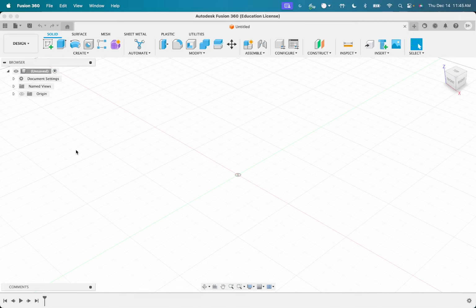Components are important because they allow you to do assembly drawings with them. You can reference them in other files, and they have more information than just a basic 3D model, which is just called a body or a mesh. Components are really important because they have those extra features. For our case, we want to set up those components now because we're creating multiple parts in our design file today. It's just better practice to lay your file out before you start.